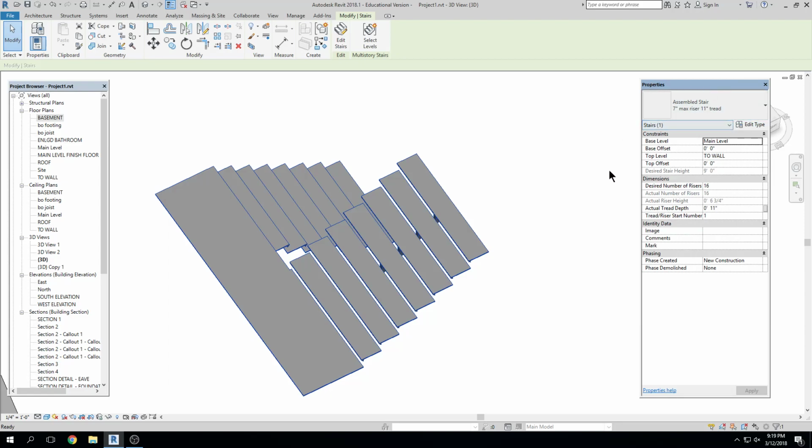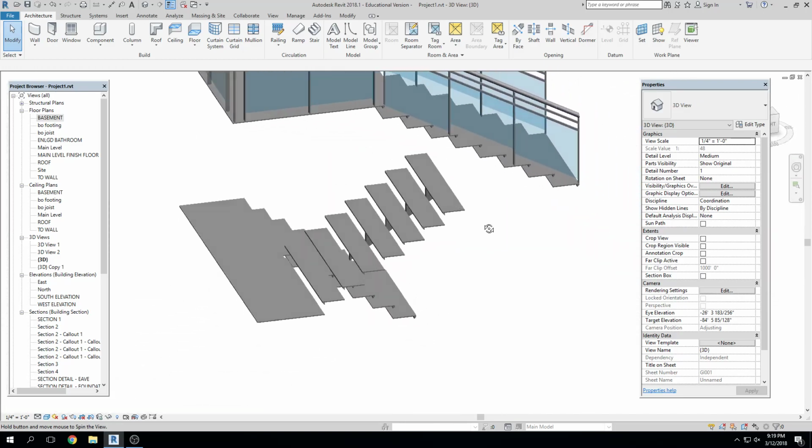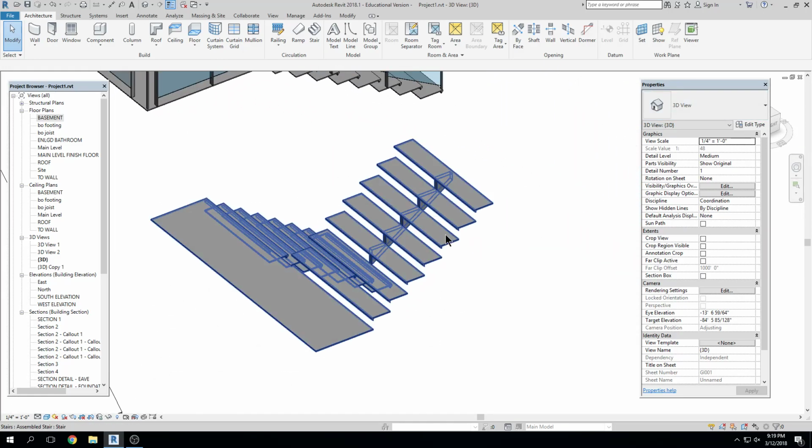Right? I very clearly changed that height, right? And nothing happened. So this stair that is defined by that type wasn't updated. I'm pretty sure in earlier versions that once you changed it, just like any other assembly in Revit, it automatically updated. The only way that I found to have these updated is to redraw them, essentially. So the next time that I drew a stair with this type, it would update it to have that 10-inch high tread or riser height, essentially.